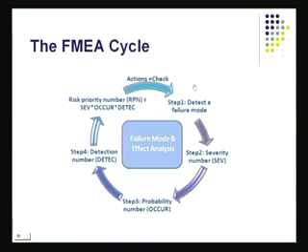And if you look at step 1, it is detect a failure mode. Try to find out what different ways a product or a component or a service can break down. So detect the failure mode and look at the severity. Look at the severity of it, which is what could be the impact. From that you'd get to know the severity of it. What is the likelihood of it, and what is the detection number? We saw all of these things when we worked on the worksheet.